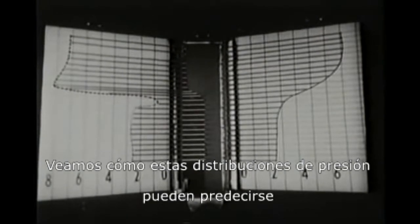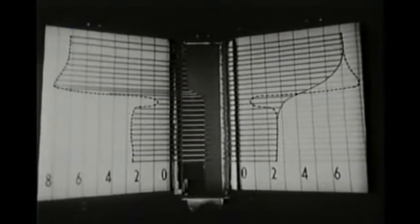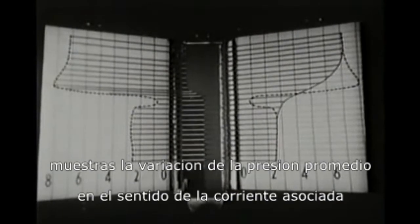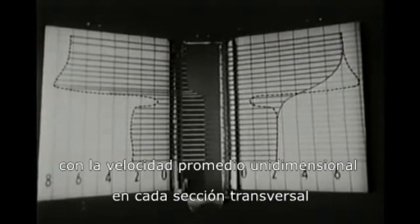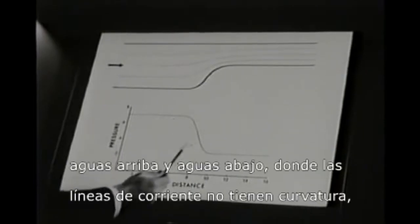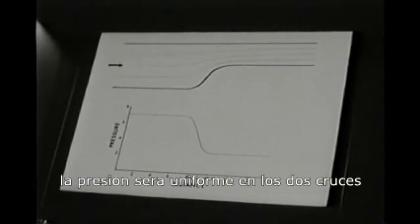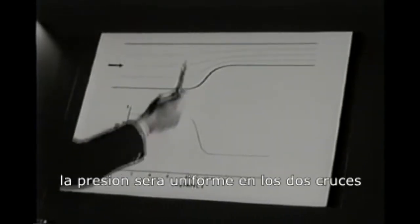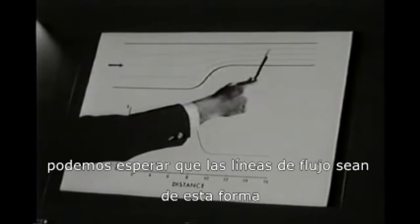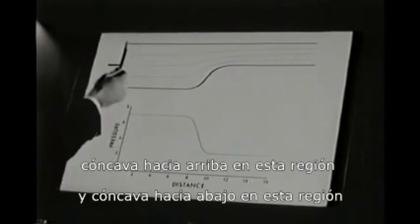Let's see how these pressure distributions may be predicted by the two dynamical equations and the equation of continuity. This curve of pressure versus distance shows the average streamwise pressure variation associated with the one-dimensional average velocity at each cross-section. Far upstream and far downstream, where the streamlines have no curvature, the pressure will be uniform over the two cross-sections. From the shape of the channel, we may expect that the streamlines will be of this general shape: concave up in this region, concave down in this region.